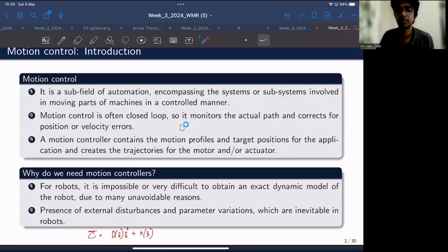But when you actually assemble a robot, there will be some joint clearances, obviously, because of manufacturing tolerances. And there could be some parts that you may not have included in the model, for example, the weight of the washers. Even though its effect is less, it could have an impact on the values of this mass matrix.